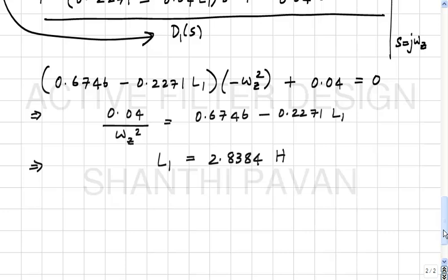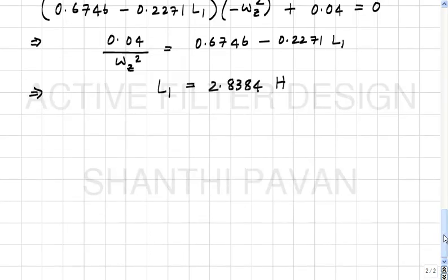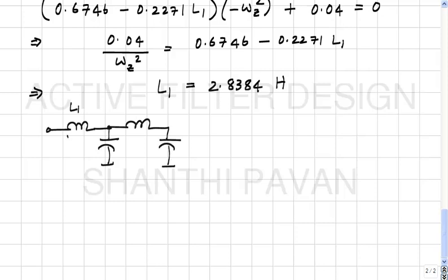Now I would like to bring your attention to what we did using the ladder when we had just an all pole network. What did we do? We first found L1, then what did we do? We subtracted SL1 from Zin. We found Zin1, which is Zin minus SL1, and that should give us the impedance at this node, right? But then what did we do?